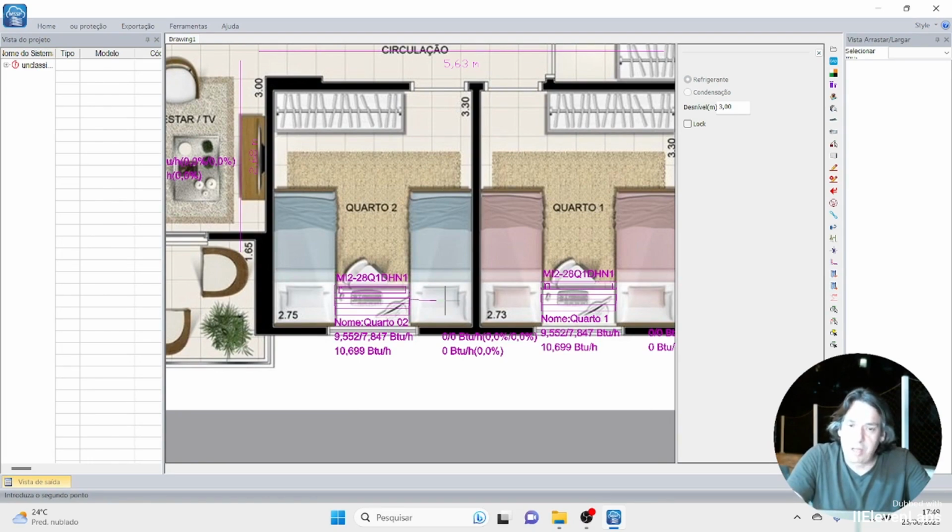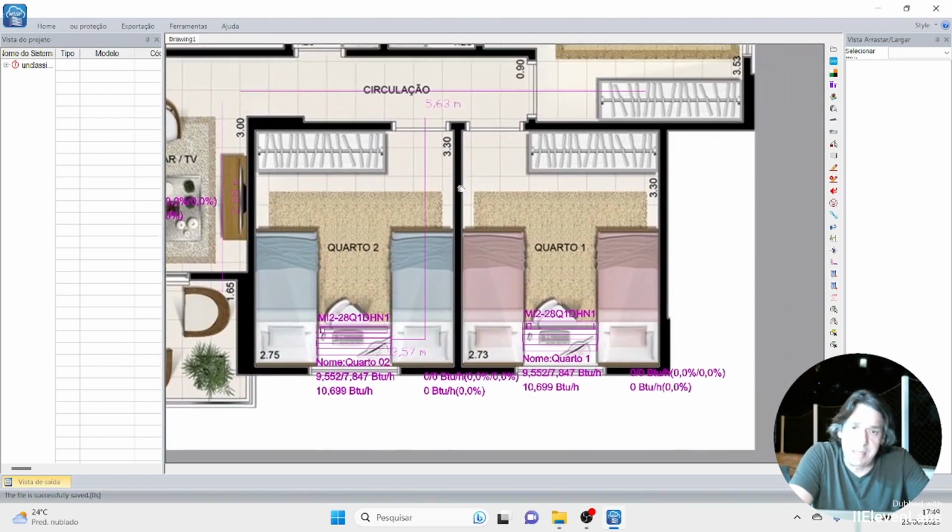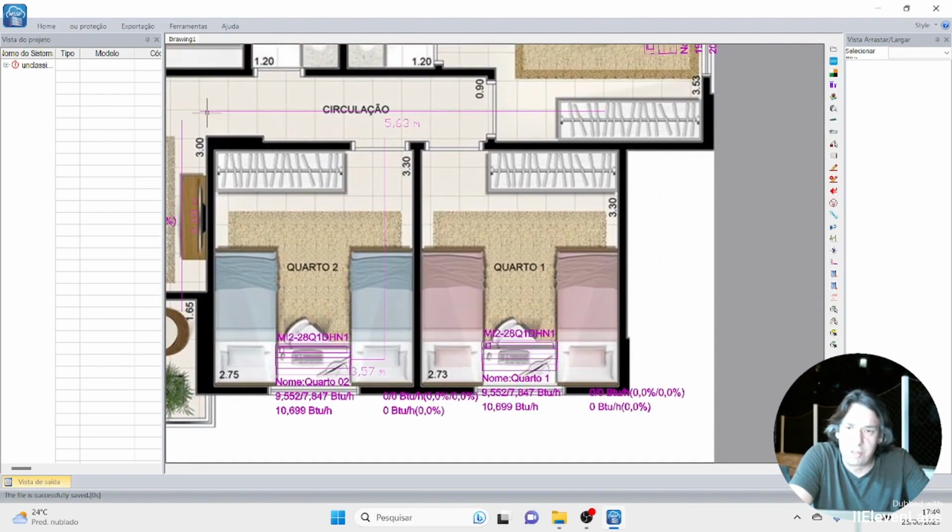To stay horizontal, press shift. It's up to here, and I go up with my tube up to here. Okay, right mouse button is my enter key, so it marks now, even if it's just the provisional length of the pipes. This pipe here is 5.63 meters and this one is 3.57 meters.